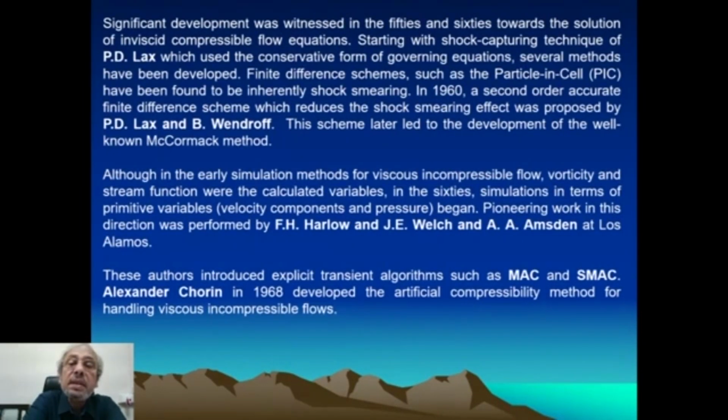Significant development was witnessed in the 50s and 60s towards the solution of inviscid compressible flow equations, starting with the shock capturing technique of P. D. Lax, which used the conservative form of governing equations. Several methods have been developed. Finite difference schemes such as particle in cell have been found to be inherently shock smearing. In 1960, a second order accurate finite difference scheme was introduced, which reduces the shock smearing effect, and this was proposed by again Peter Lax and Wendroff. The scheme later led to the development of the well-known MacCormack method.